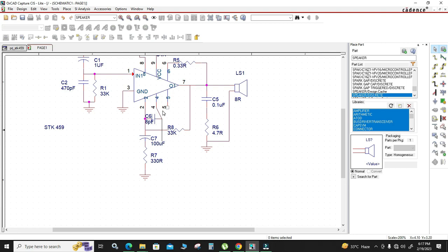So that's how we check. How can we check? It shows this net name N02211. Then when we check this other net name N02220, the two are different. So it means these two nets are different, so it does not have any connection.